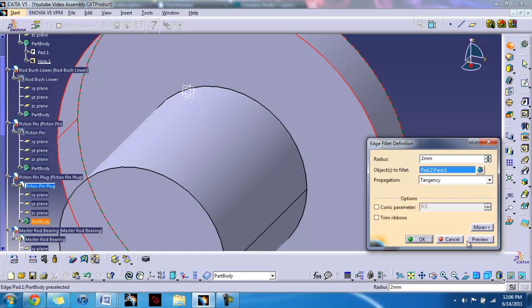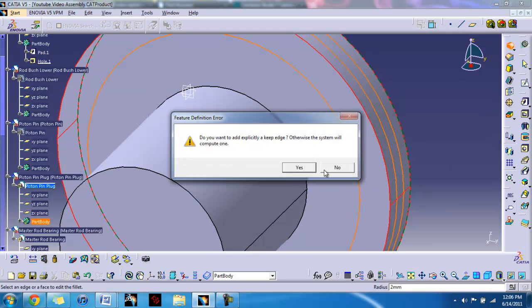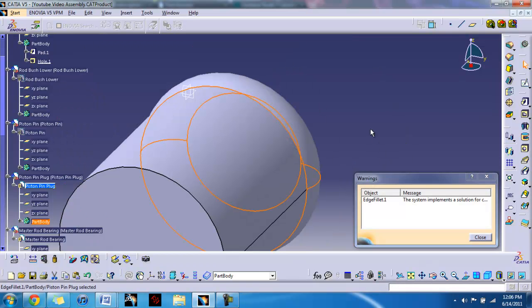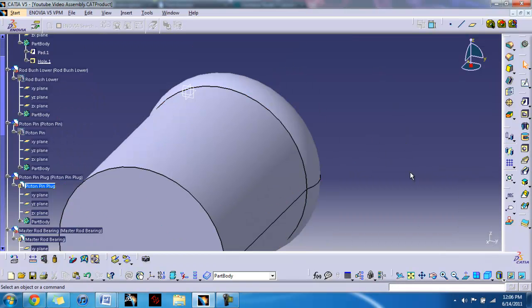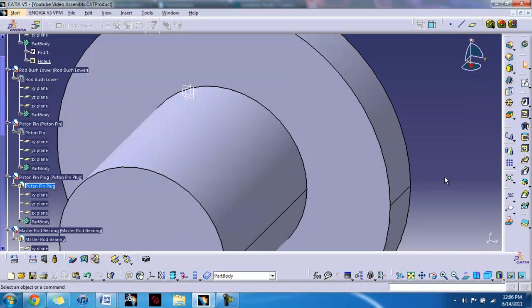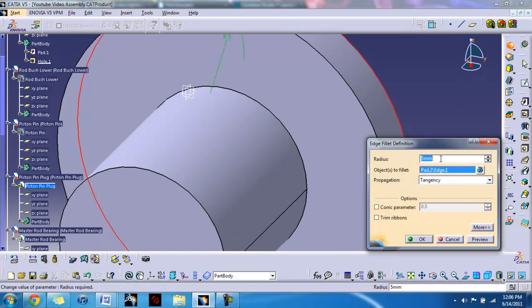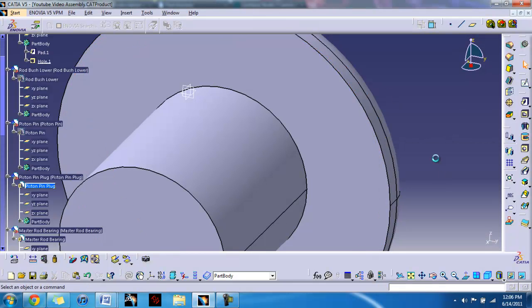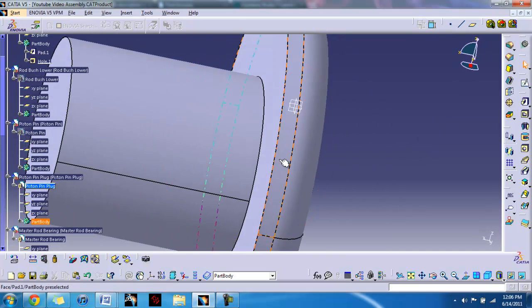And that last pad had a diameter of 11. Now we're making the fillet. Making sure you select the right edge, because if you don't, that is what will happen. So you have to select this top edge. And that has a radius of 2. And now you're done with the plug.